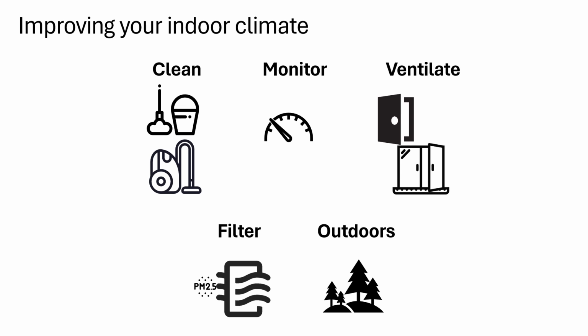Maintain and use appropriate ventilation systems, and where possible use natural ventilation because that's more energy efficient. Implement extra air cleaning measures using portable air cleaners, especially during poor outdoor air quality events. When needed and outdoor conditions permitting, we can move some events outdoors because outdoors provides a much faster dilution than you can get indoors.